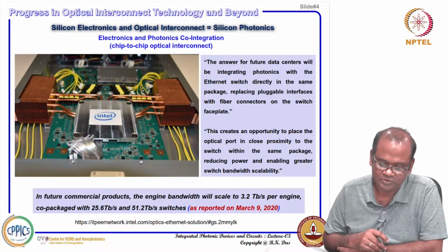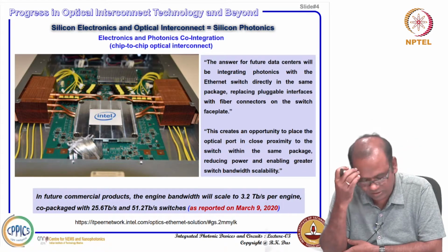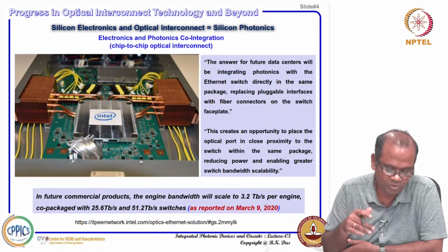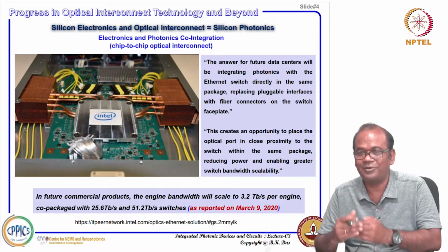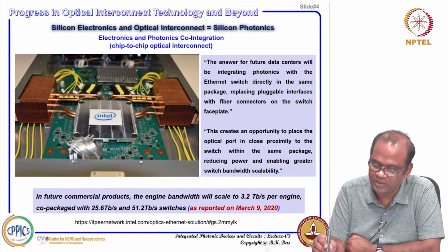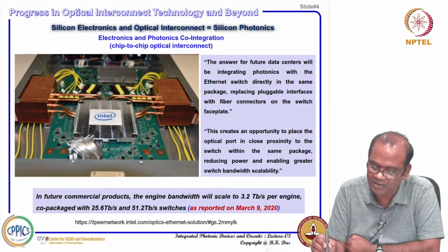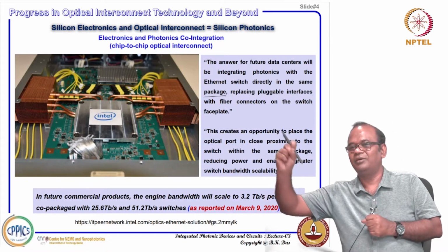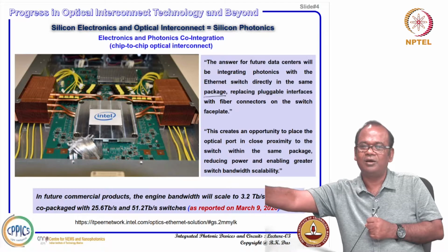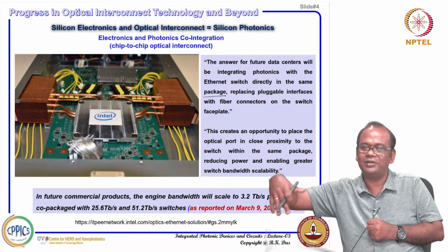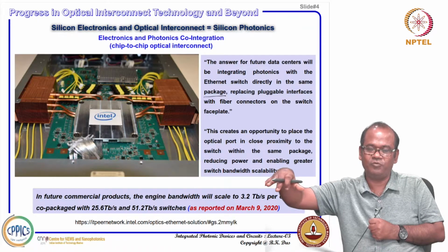So, chip to chip communication. This type of transceiver module they have used for chip to chip communication, one chip to another chip, not rack to rack, chip to chip. They say that the answer for future data centers will be integrating photonics with the Ethernet switch directly in the same package, not that you take out fiber and then go a few hundred meters or a few meters, and then another transceiver will be there and they are giving feedback, giving input, right.